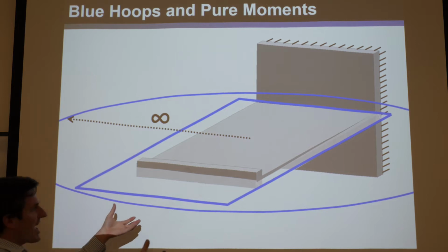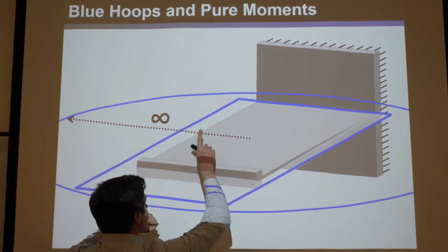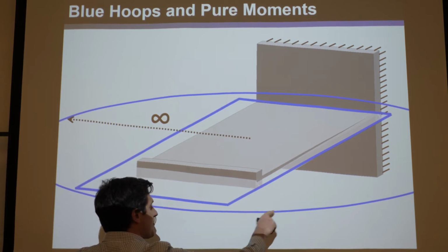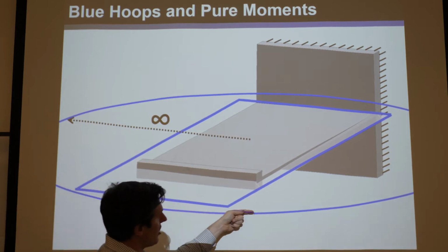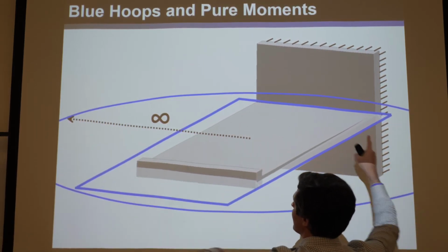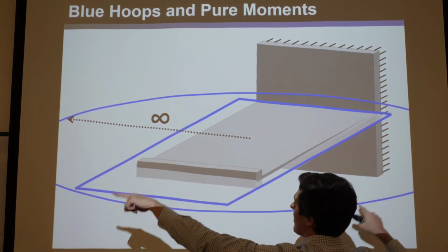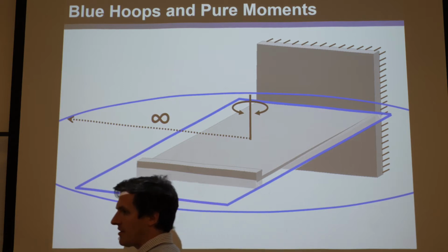Okay, remember when it's red, you think of it rotating and you imagine it rotating, so you can imagine a translation. But now this is a pure force. So now imagine pushing along its axis with a pure force in a circle. If you're pushing with a force in all these directions, what you'd get is a pure moment.